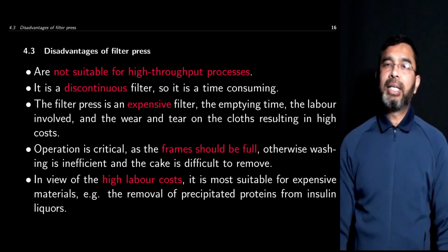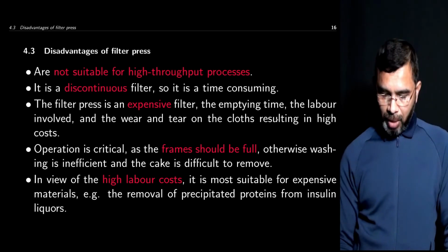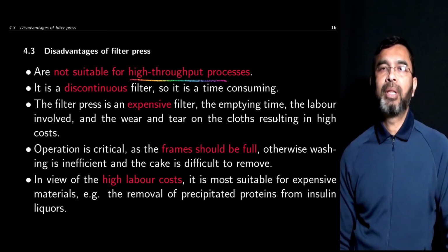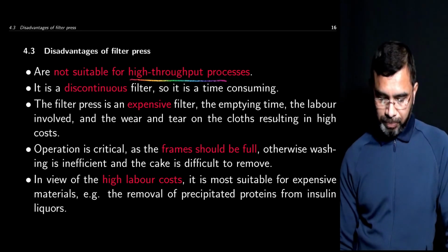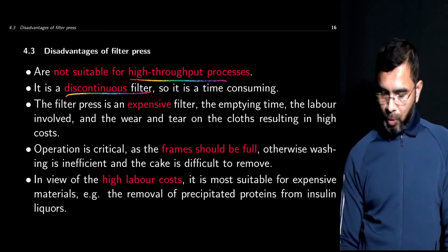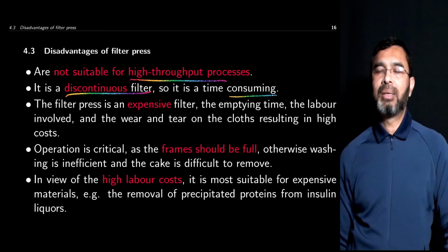Saying that, there are certain disadvantages of this operation. One is that the flow of filtration may not be very high. So if you require a very high throughput, this may not be the perfect equipment for filtration. It's a discontinuous process. So in that sense, it's time consuming. You need to dismantle the process, then clean it and reassemble again.